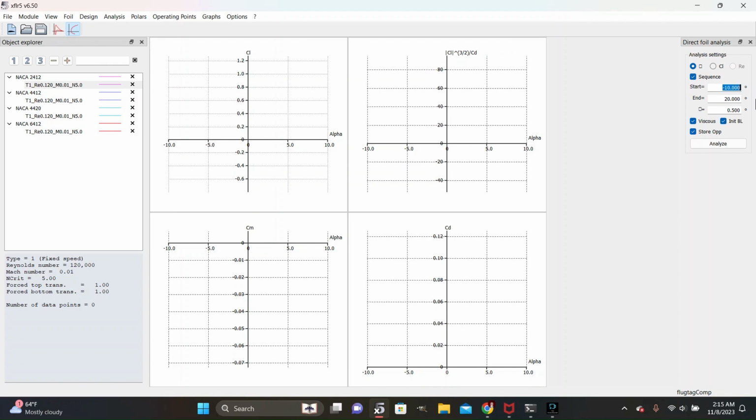And I'm going to run this at a sequence of -1 to 1 degrees, with a change of 0.2. So again, I'm going to be flying it mostly flat, and I just want to see how it performs in those ranges and get some detailed responses, which is why my increment is so low.